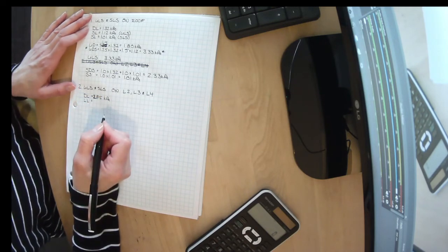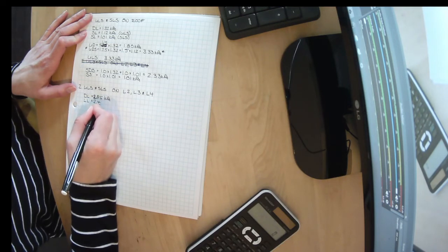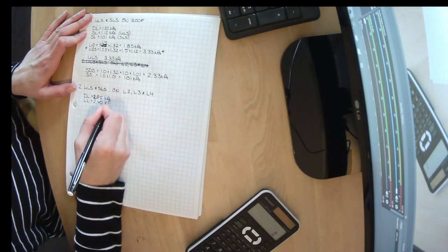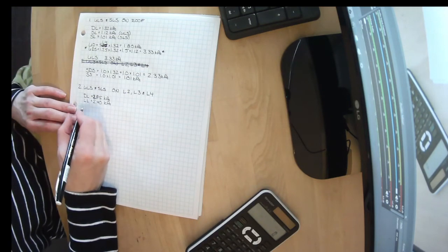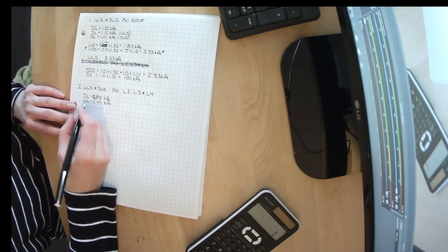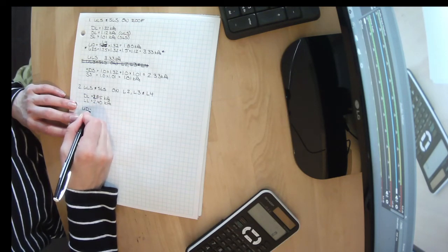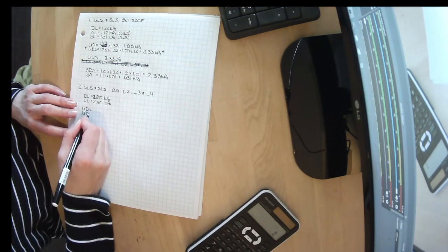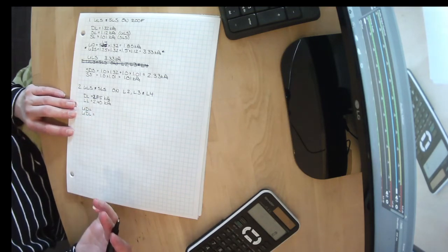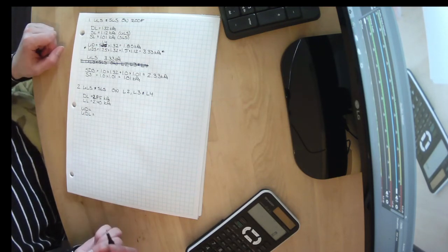We were also told that it was an office building, and we looked up that live load for an office building is 2.4 kPa. So we need to figure out what our worst case ultimate limit states load case is, or our ultimate limit states dead, or our ultimate limit states dead plus live. We could add snow here, but it would be 1 times 0.